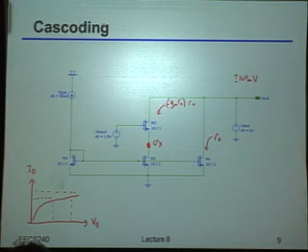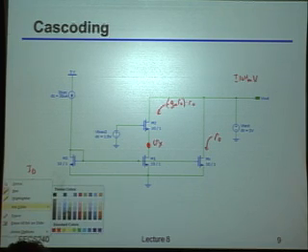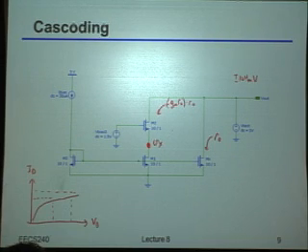Well, with the cascode, which now I'm just going to do in a different color so it's easier to see, let's take the particular example that I gave. Let's say that indeed I was interested in this plus minus 100 millivolts variation on the output. How much variation would you see in Vx for that same plus minus 100 millivolts at the output? I don't need a number, just parametrically. Yeah, exactly. It would be gm*RO times smaller swing.